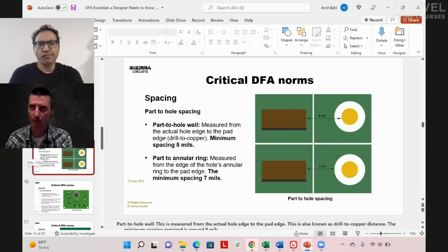I think you can use like 0.075 millimeter. I don't know. It's like three mils. That would be a lot. I was going to say like a third of that. 1 mil. Okay. But yeah, more the better. So you can make a small opening around the pad as 1 mil, and the PCB house can still manufacture it with no problems.